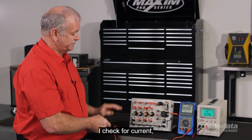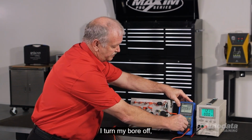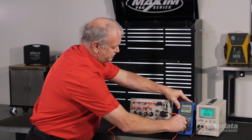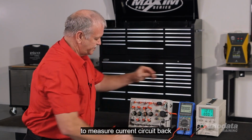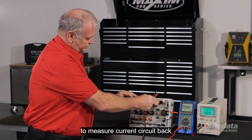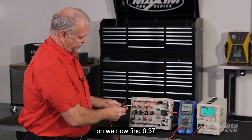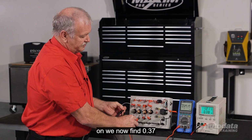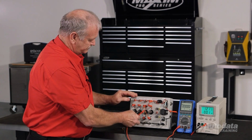Now I check for current. Turn my board off. Set my meter up to measure current. Circuit back on. We'll now find 0.37.